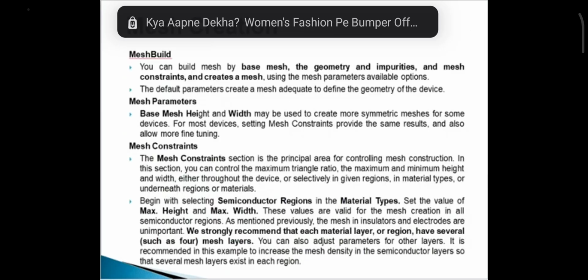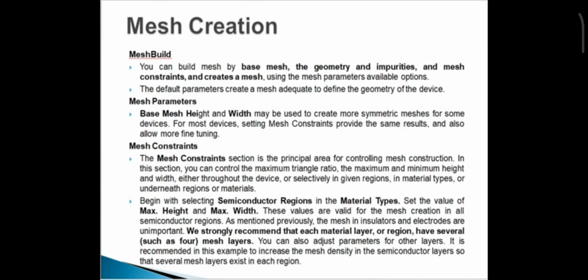Next is how to create mesh in the DevEdit. Mesh build. First point, you can build mesh by base mesh, the geometry and impurities and mesh constraints, and create a mesh using a mesh parameter available option. The default parameters create a mesh adequate to define the geometry of the device.